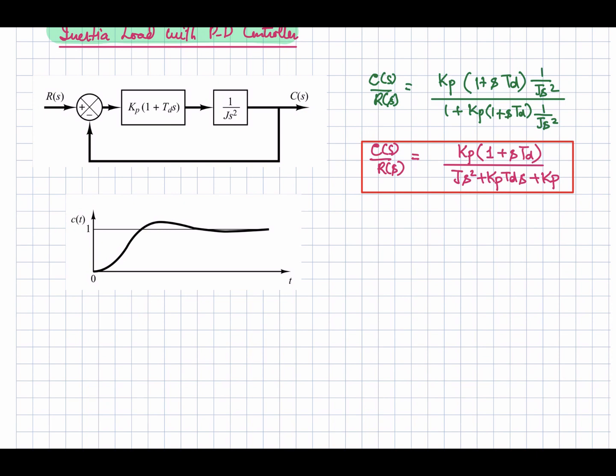Okay, so derivative control action when added to a proportional controller provides a means of obtaining a controller with high sensitivity. An advantage of using derivative control action is that it responds to the rate of change of actuating error and can produce a significant correction before the magnitude of the actuating error becomes too large, right?